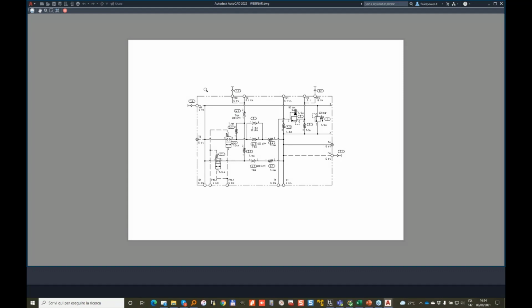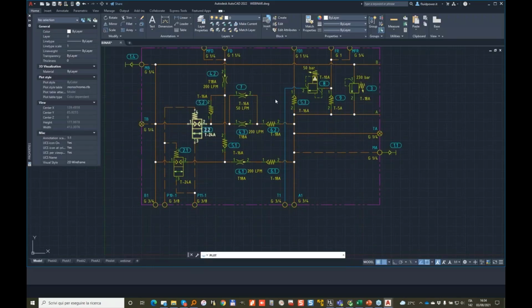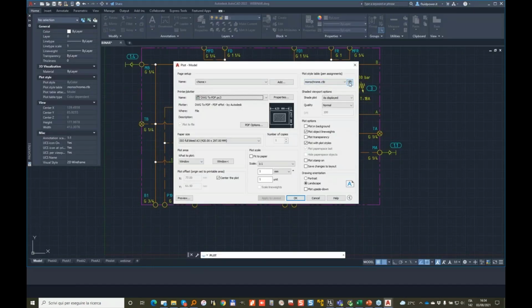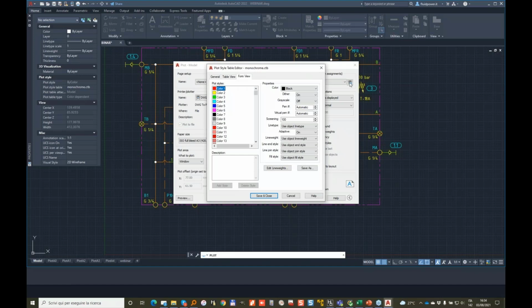Yes, so that color, if you see entities that do not get plotted black and white in color dependent, that means that that color is not mapped in the table for color dependent. So in this case, you can check the colors in the table by clicking and defining the color. In that case, there was a color missing. So what I did was just specify a different color for that drawing entity, and now everything is black and white.